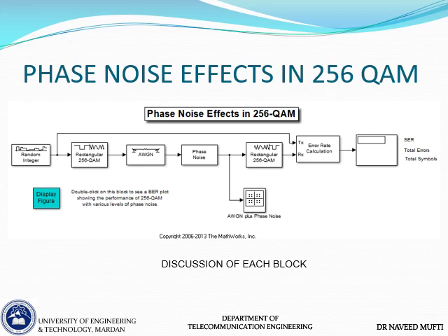It is modulating the amplitude and phase of this analog carrier. Now the modulated carrier, one of the symbols in every symbol interval, will pass through the channel. We have taken an AWGN channel, as it says here. And then we've also added phase noise. So the channel itself is noisy, which is introducing noise in the amplitude, and we've also added this block which adds phase noise to the system.